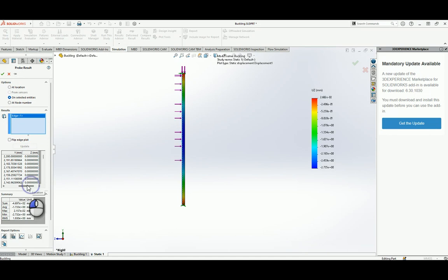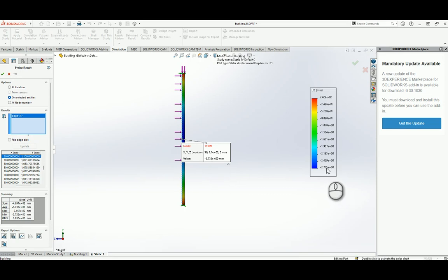Alright, just as a check, you can look at y equal to 1100, again, which is the middle point of the beam. And we could see minus 2.732, which is what we expected to be around our maximum. Right, remember, it may not be the exact point. It has 3.2 and the maximum here is 3.5, and again, that's because 1100 millimeters is not the exact center because we had the whole hinge at the bottom.